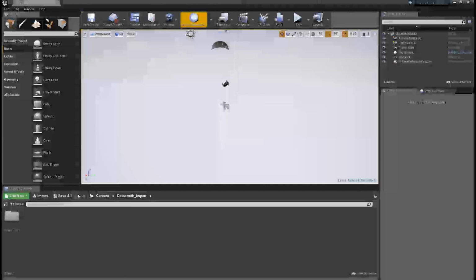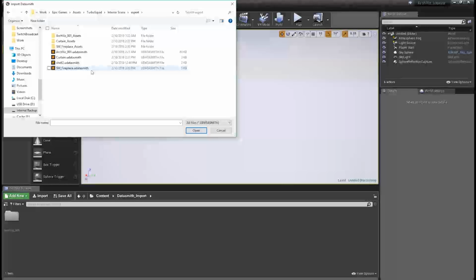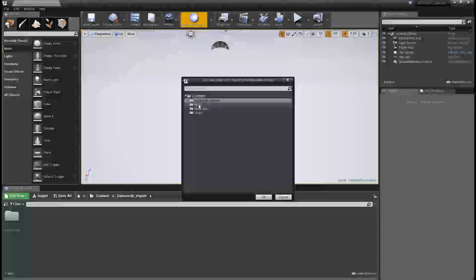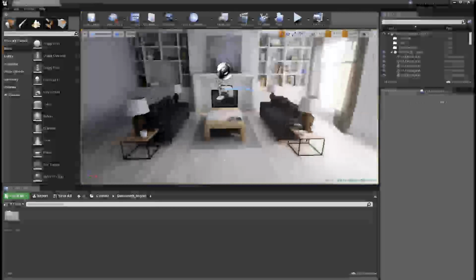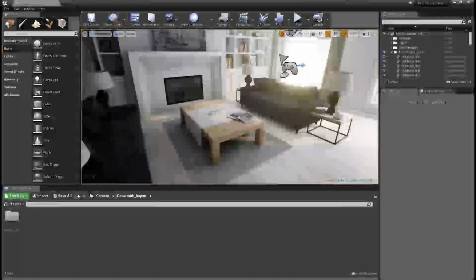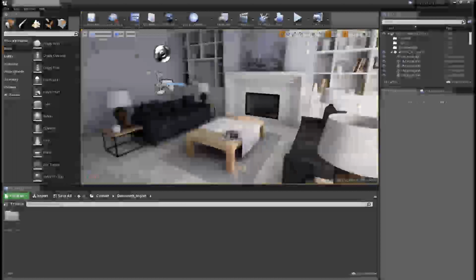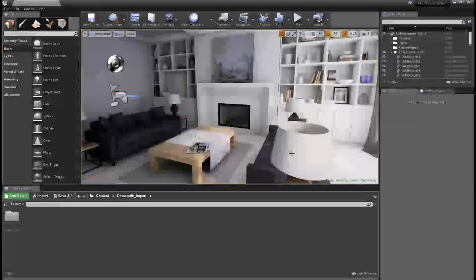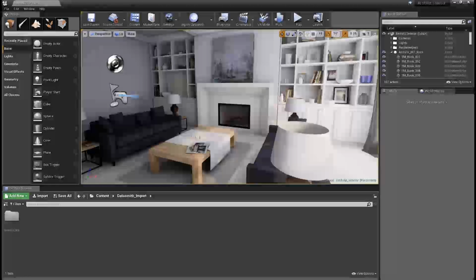And remember, sending the entire scene at once using Datasmith means everything will already be set up in the correct locations. So adjusting pivot points isn't actually necessary for Unreal to be able to import your assets. Unreal is very forgiving in that way. But making sure you've set your pivot points up in this manner will make moving and rotating those assets in Unreal afterwards a lot more consistent.